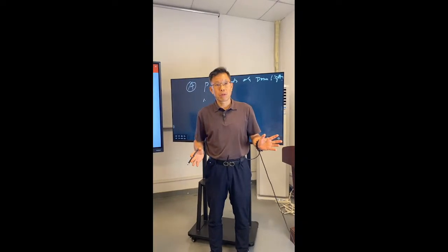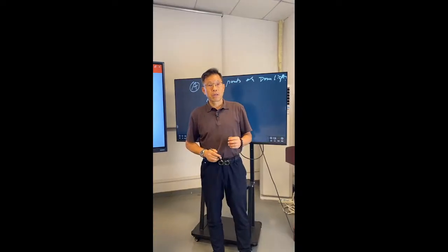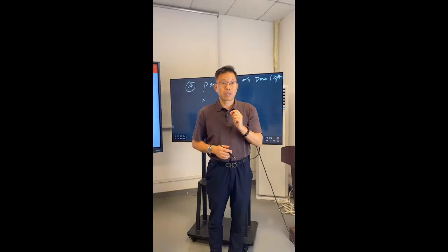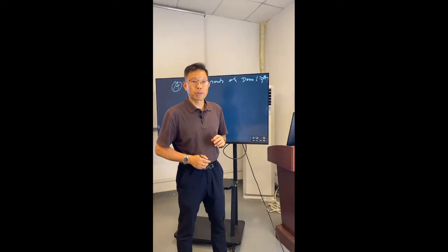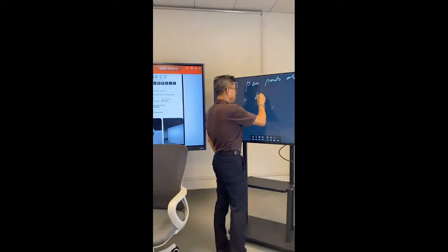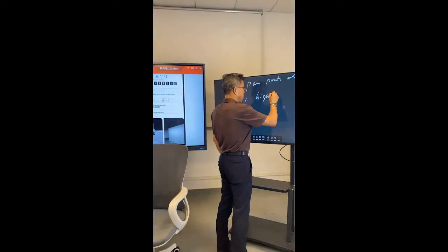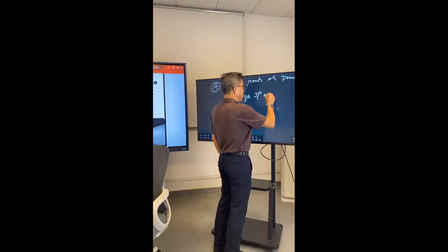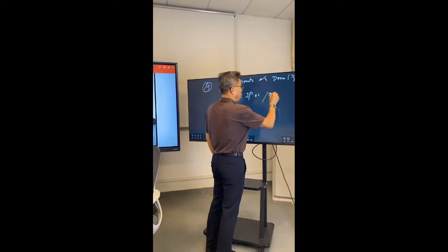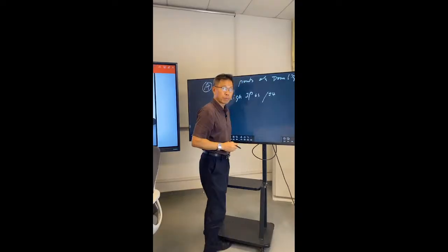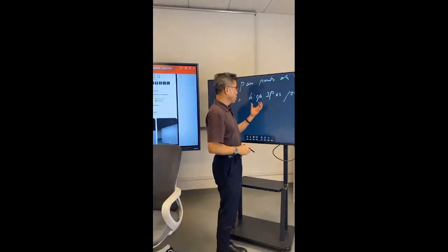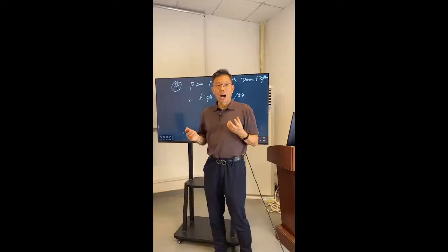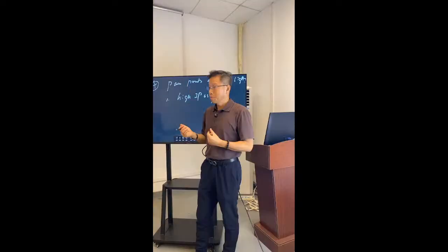In these areas, users need high IP grade downlights, that is, high IP is a need. That is IP65, IP54. So the first concern is people need high IP grade downlights.